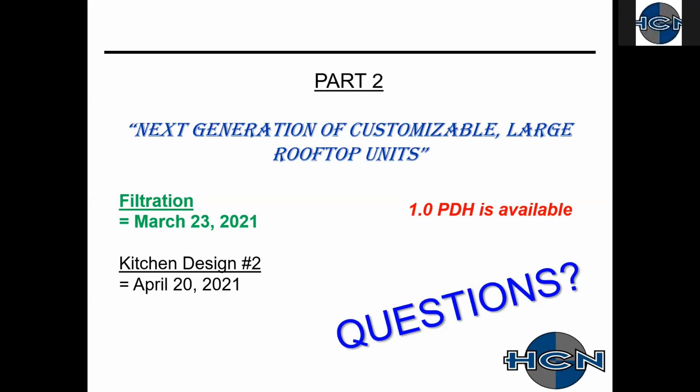Jim, if I could add here, one of the main reasons they're switching, and they haven't done this across the board yet, is that parallel reheat will give you more reheat capacity, and we're seeing this as a driver in grow room applications.